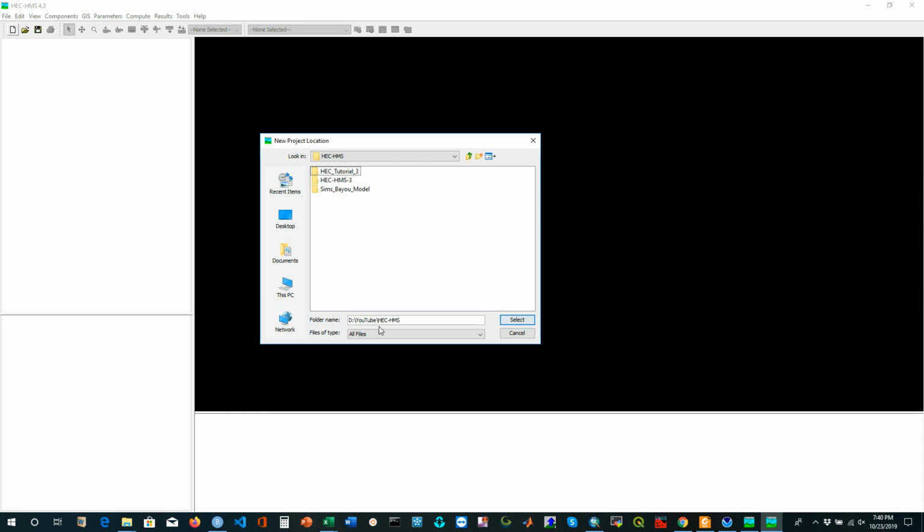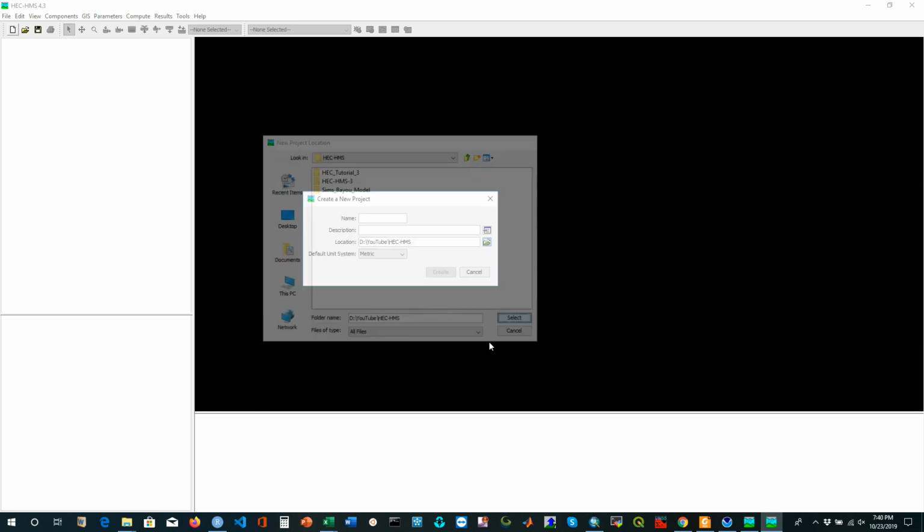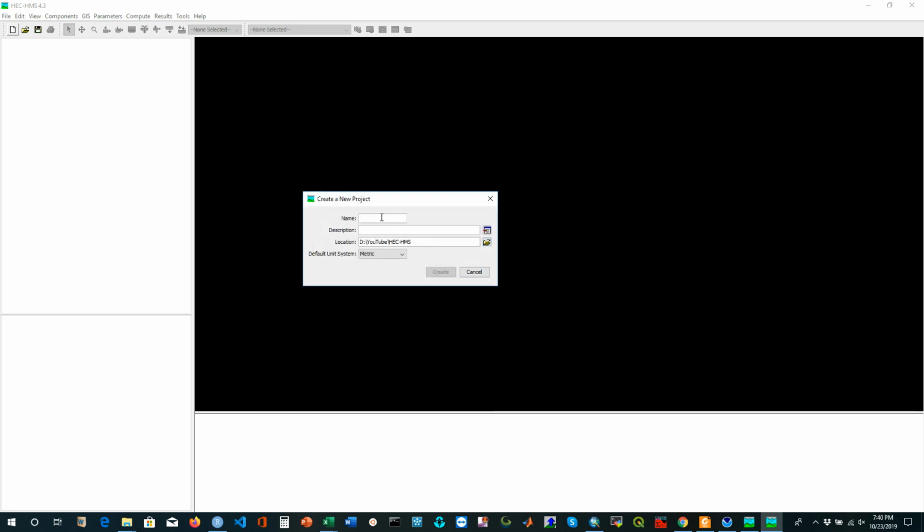HEC-HMS, and then I'm selecting this folder. You can give the name of the project folder. So it is tutorial 3, right? And you have to select your model units.